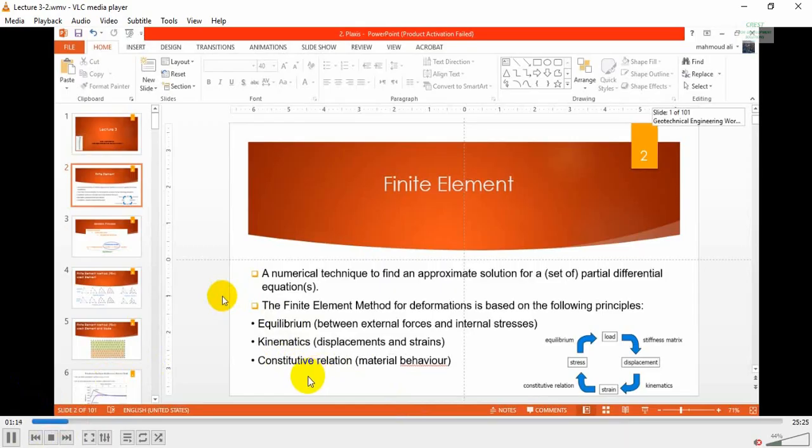To understand, Plaxis performs its calculations in steps. Each step represents a percentage of the applied external load. For each step, the displacement corresponding to the applied load is calculated through the stiffness matrices.